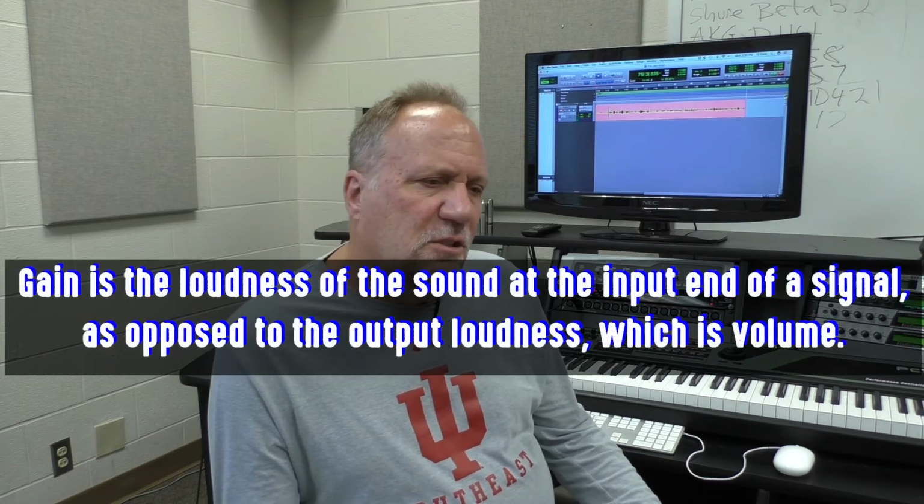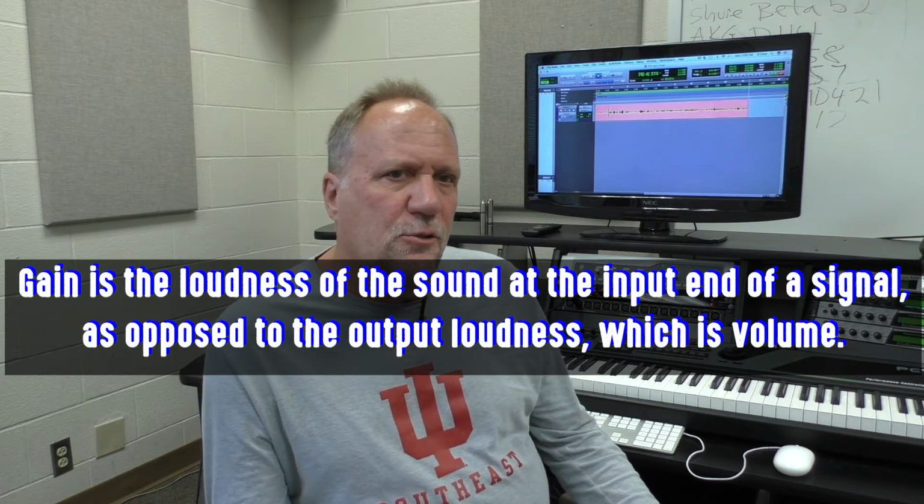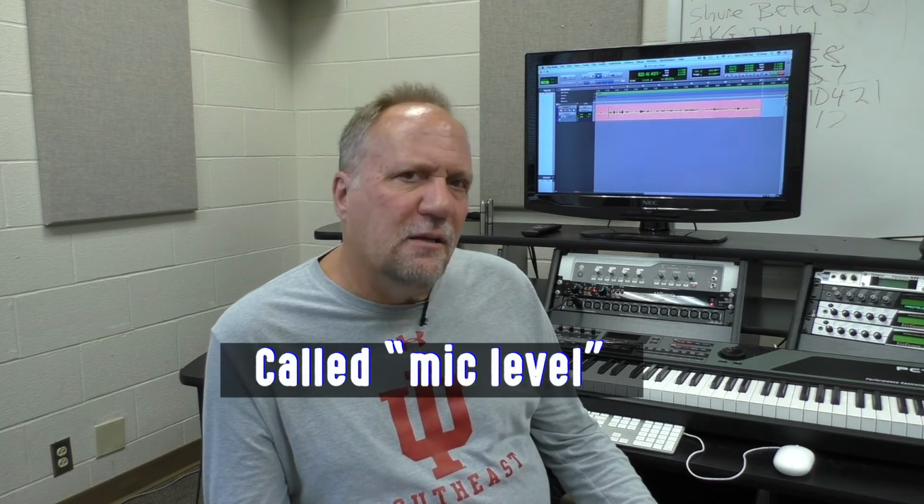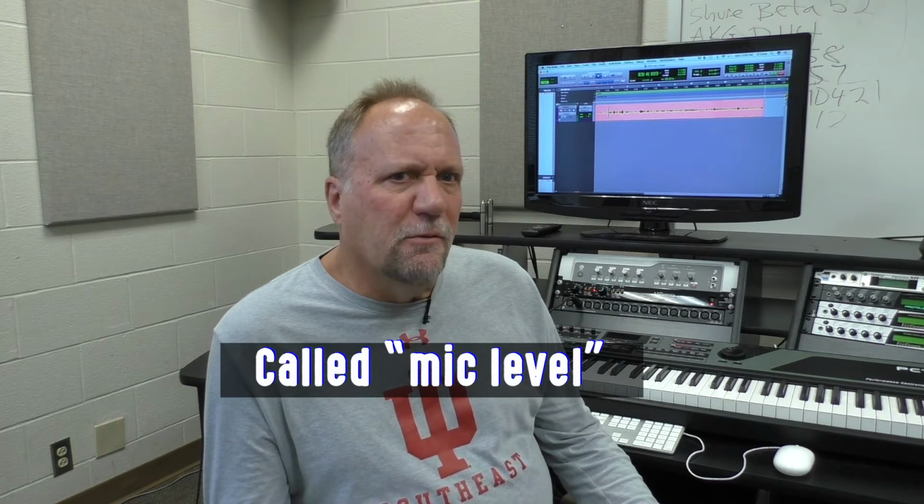When the sound wave is converted to that alternating electrical current by the microphone transducer, it's at a really, really, really low voltage level. In fact, it's what they call millivolts, or thousandths of a volt. If you take a 9-volt battery, stick it on your tongue, you can feel a little tickle, right? If you took the output of a microphone and put it on your tongue, there's absolutely no way that you would feel it. Plus you'd look really weird. So you have this millivolt signal.